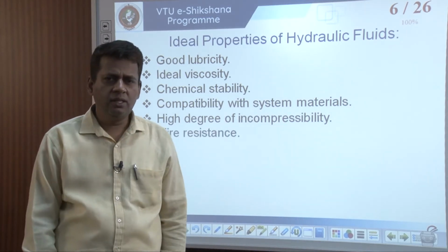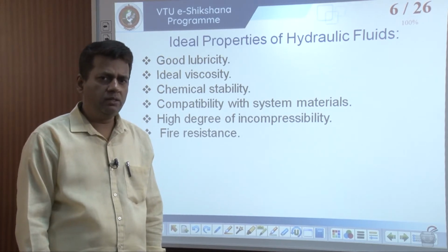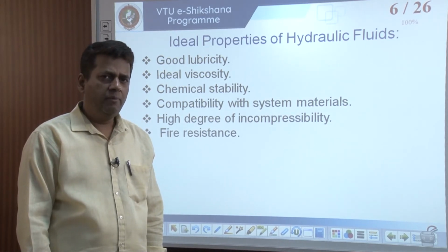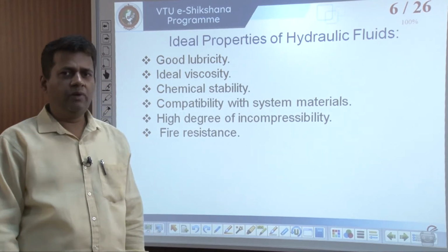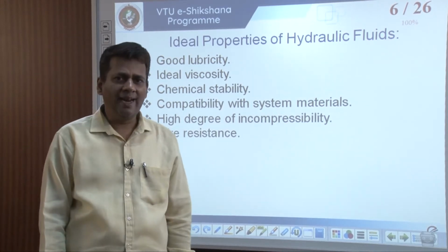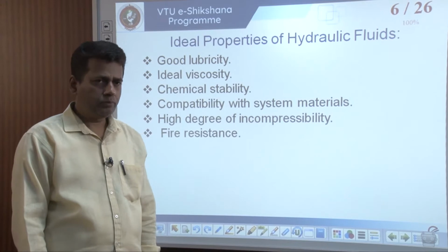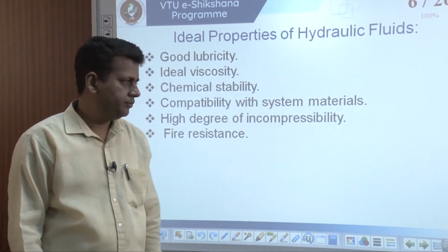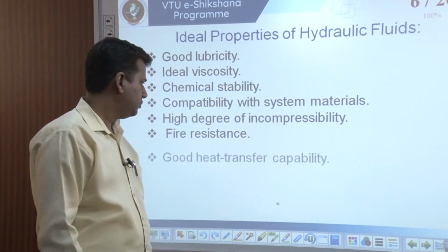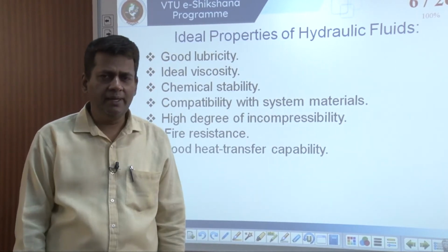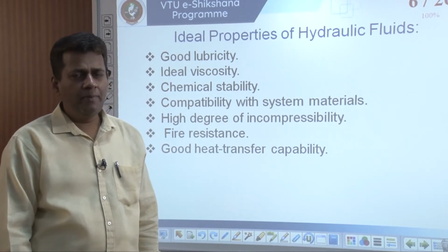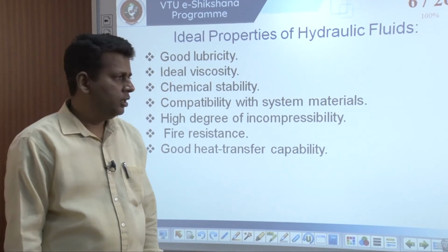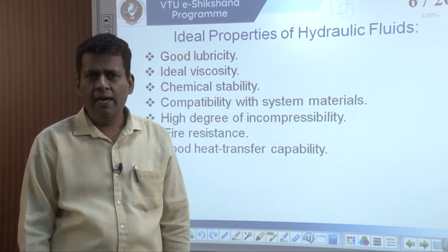Fire resistance. See, fire resistance is very important because the hydraulic fluid itself may catch fire sometimes because of low flash and fire point. So, we need to investigate the flash and fire point. For that, we need to conduct rapid tests on the oil samples and we need to find out the flash and the fire point and take corrective actions. Good heat transfer capability. So, the heat dissipation capacity depends upon conduction, convection and radiation.